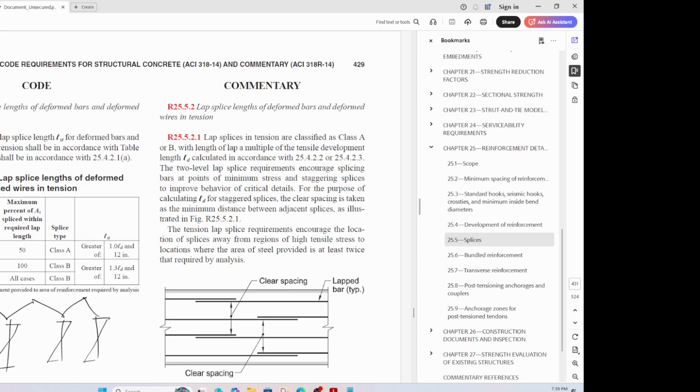So you find out the reinforcement from first principles. You find out the area of steel required. Now you provide that area of steel here, not only here, but then you continue it along the entire length. So at a section like this here, the bending moment is only 50% or 40%, something like that.